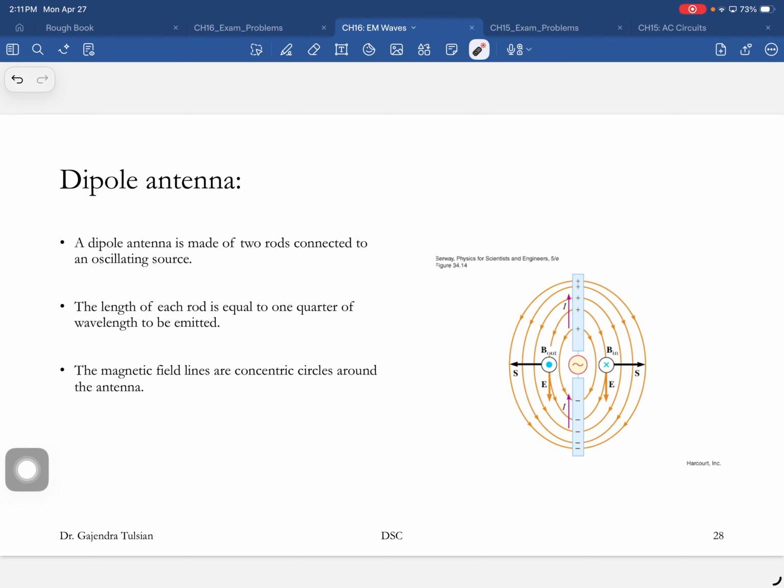You superimpose the signal over the carrier signal, which had uniform amplitude, and now the combined signal is the red signal. That's the signal that's transmitted. Then you receive it, and you separate this from the carrier in the radio. The problem with this method of transmission is there's a lot of noise. Random signals can cause noise and interference.